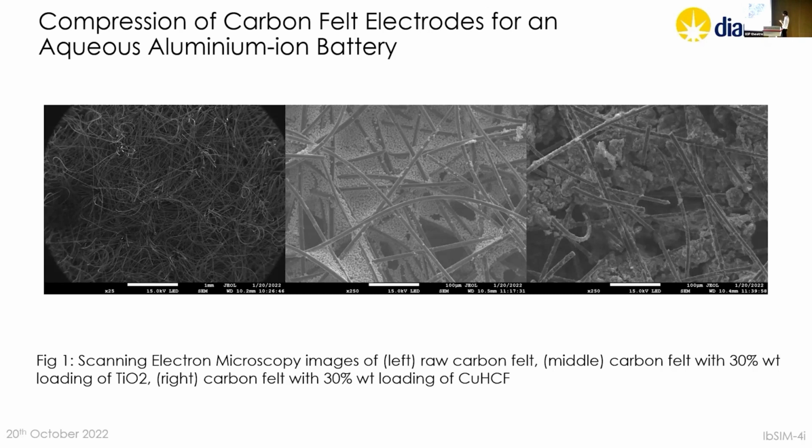And they typically use these types of carbon felts as the electrode structure. So on the left-hand side, you can see this fibrous formation. And the trouble is the electrical conduction is linked to the connection of these different fibers. So typically what the electrochemists do is they squash these things to get more conduction. What that does is it closes off the pore space involved in this structure, and that's how the ions are diffusing through. So you've got this interplay between electrical conduction and ionic diffusion in these two different phases. And what we're interested in doing is trying to characterize that.